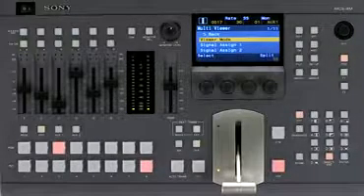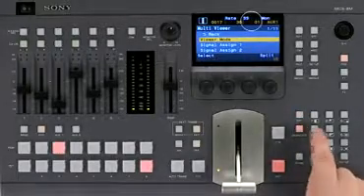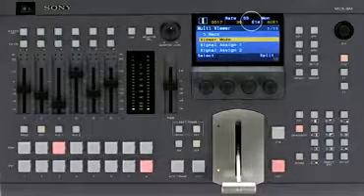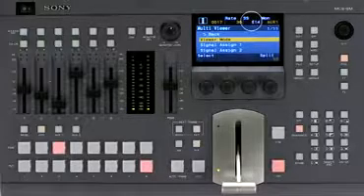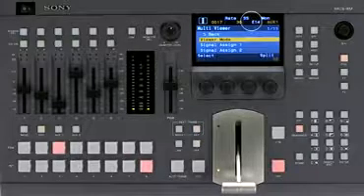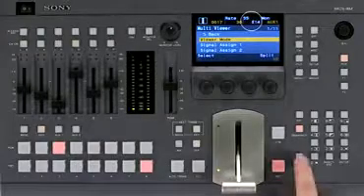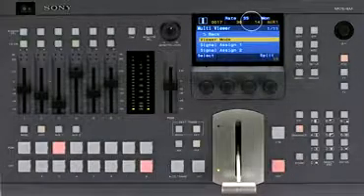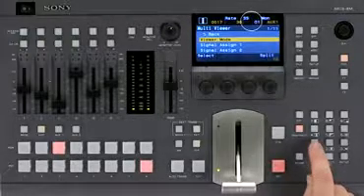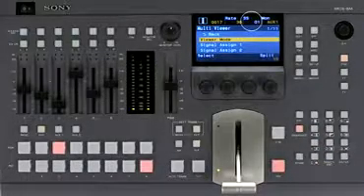To store a snapshot to the switcher, press the Snapshot button. Enter the number, 1 to 20, under which to save the snapshot. The number entered appears as the snapshot number in the menu screen. If a snapshot is not currently registered to the number entered, empty will appear to the left of the number. Press the Store button. The snapshot is registered. If you enter a number that is already in use, the previous snapshot will be overwritten. Snapshots can be imported to and exported from USB.